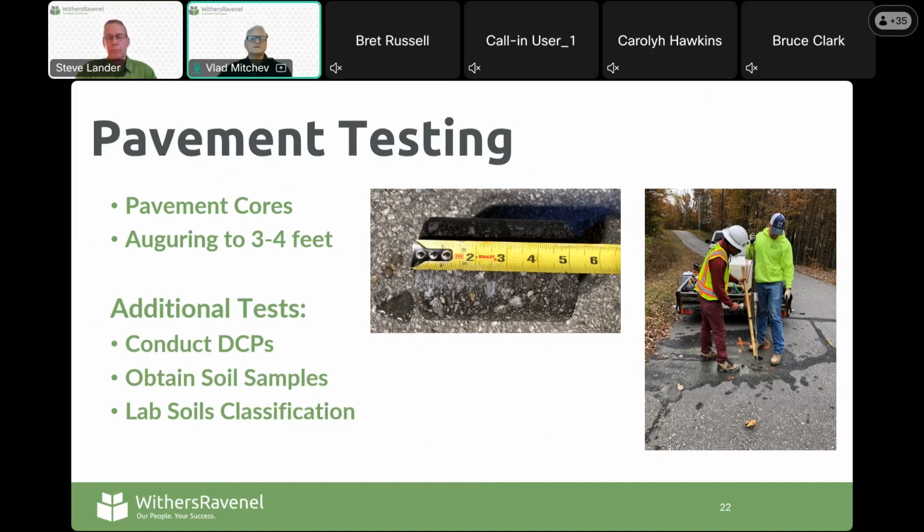which is a really good property to know about the soil, because based on the CBR value, you can do pavement design or estimate remaining structural life, if that is something really needed for that section.